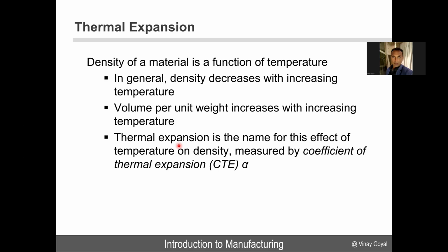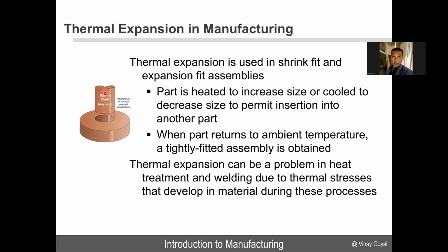Also, thermal expansion is important for creating tight fit connections. Here's an example of what I mean. Thermal expansion can be used in shrink fit and expansion fit assemblies like this, where you're trying to develop an interference fit for the required application. What we do there is the part is heated to increase the size or cooled to decrease size, and that permits insertion into another part. When the part returns to ambient temperature, you get that tight fit assembly you wanted.